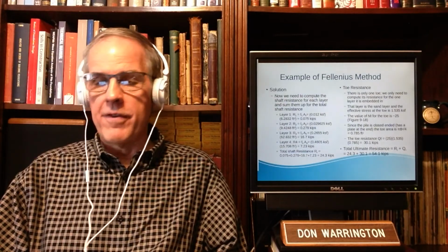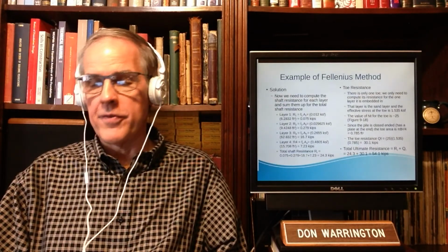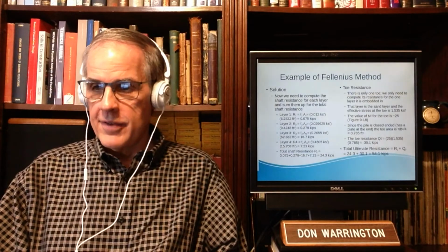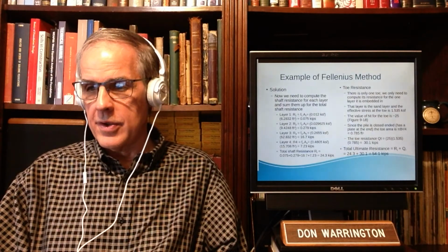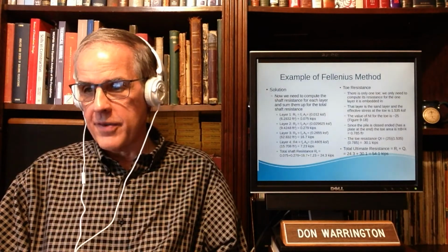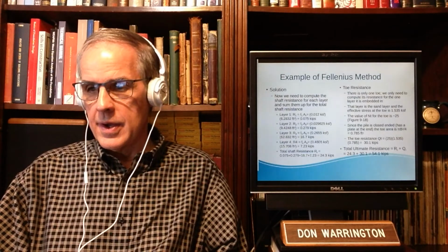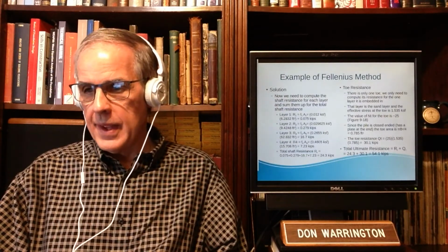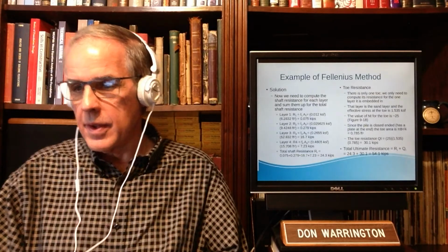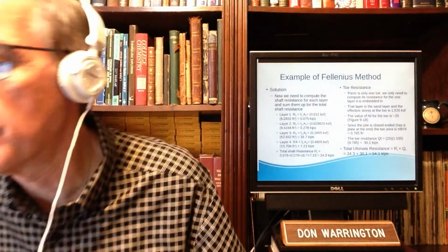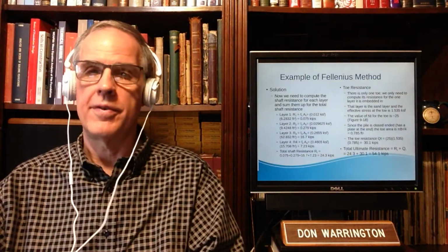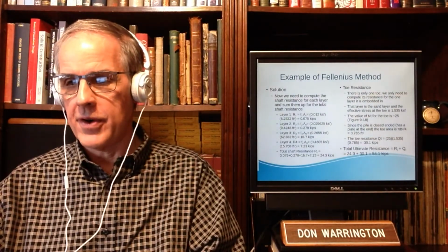The sand layer, the effective stress at the toe is 1.535 KSF. The value of N sub T at the toe is around 25, from Figure 9-18.